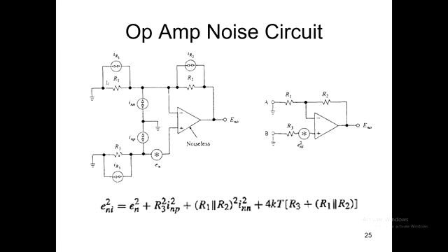And it's convenient to think of the noises in the resistors as being parallel currents, because then we can imagine that the output of the op-amp is a ground point again. We can imagine it grounded through its equivalent output voltage generator. So this current source and that one are both in parallel with each other in effect. This one down here does its own little bit through that resistor, creating a voltage that gets summed with the op-amp's internal voltage.